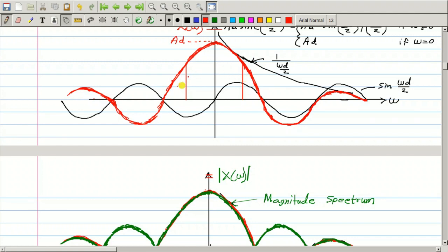amplitudes which are complex conjugate to each other, because these complex exponentials are like spirals that rotate in three-dimensional space we have discussed, and the one with positive frequency rotates in the opposite direction to the one with negative frequency. If and only if their amplitudes are same and they start from symmetric opposite position, then their imaginary part will cancel and only the real part will remain. That is required because the given signal x(t) is real.